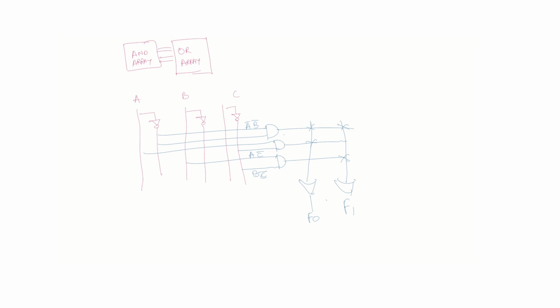You can use De Morgan's theorem and write the same function as the complement of the complement of M0, M1, M4, M7 terms. These are all active low outputs you get from the decoder, and you can directly connect them to a NAND gate: M0, M1, M4 and M7. This is your Z output.